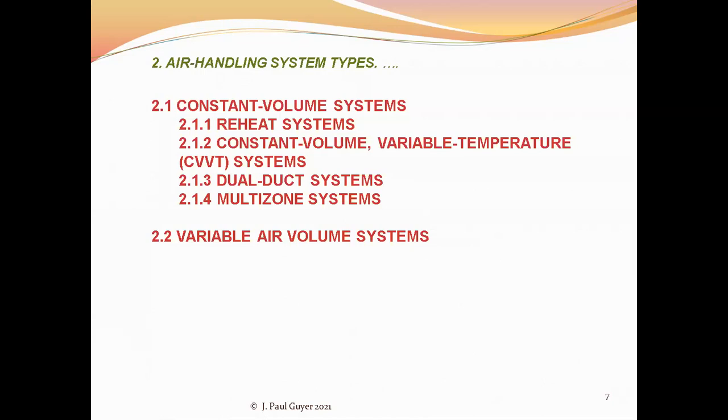So the bottom line with this type of multi-zone system using dampers is that these zones are fighting each other, because there's just a constant volume of air that's coming out of the fan, and the zones are perhaps in competition with each other. And so that is energy inefficient, and also it can be somewhat ineffective as far as delivering comfort to the occupants.